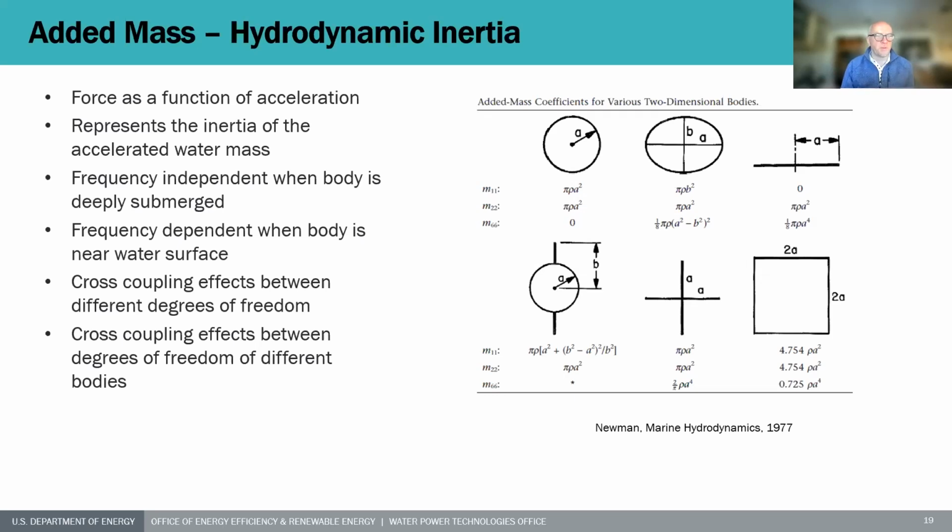It is a force that is in phase or a function of acceleration. That's why it neatly can be interpreted as an inertia, and that's a valid interpretation. It is the inertia of the water that needs to be moved while the body is moving. It is frequency independent when the body is not in the vicinity of the free surface, but it becomes frequency dependent when the body is close to the surface.